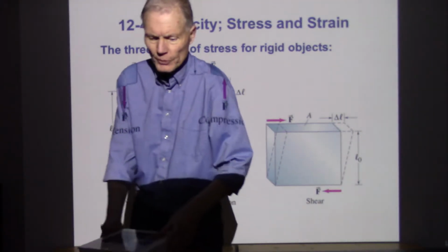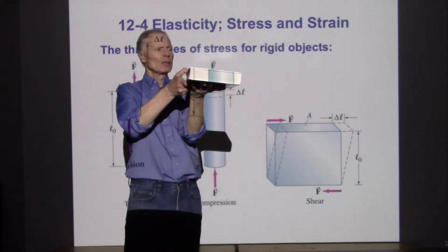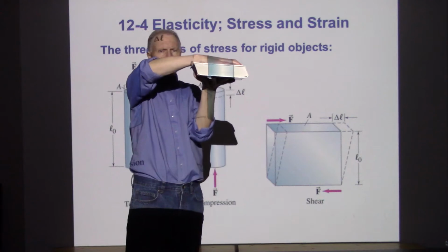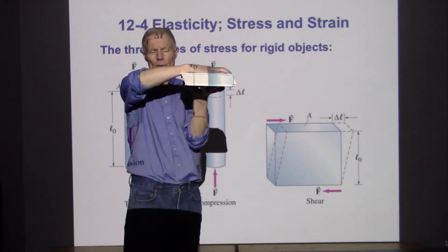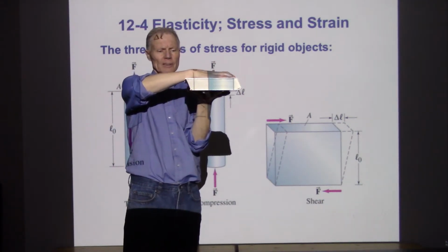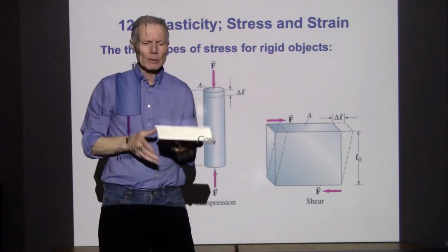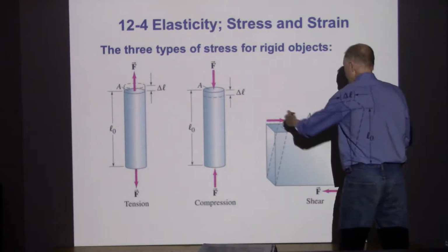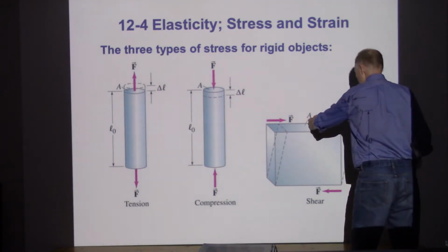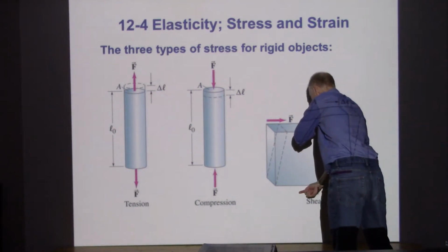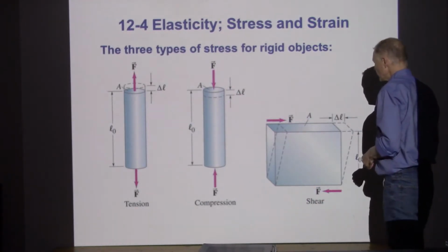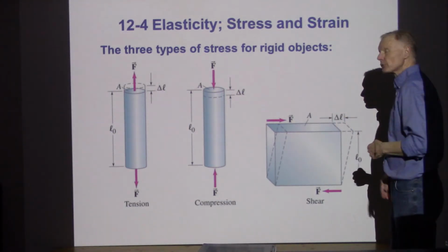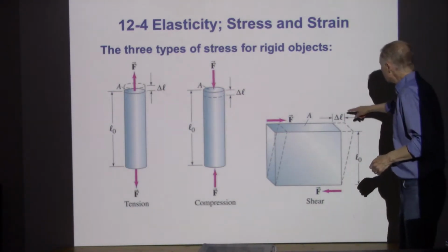Textbooks are good for this because you can say, okay, here's a textbook. What would happen if it underwent a shear strain? And a shear strain would change its shape. Now it's back to normal. Now there's a shear stress on it. And so the shear stresses, I've got a force that's to the side here, and then at a different location, the opposite direction. So what it's doing is it's tending to tip the object, or it's straining the object by an amount